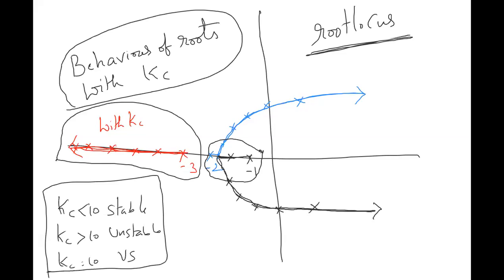So this is where we will see, even for Kc less than 10, this is where the systems are stable. Up to Kc less than 10, all the systems are stable. But when Kc is beyond 10, I don't have any problem with this third system. I have a problem with systems 1 and 2. So it gives you the detailed analysis of the systems, that is, which systems you have to be careful about in the control loop. Let's say 1 and 2 correspond to the measurement and final control element. Then you have to be careful while operating these things. Clear?